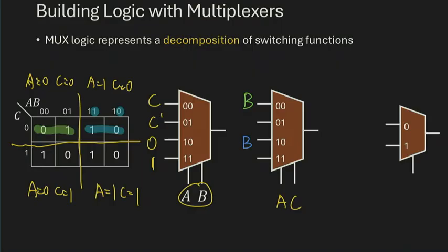And what about the next? Well, I can do 0, 1. Output is the complement of B. So I put down the complement of B. And finally, the last bit, 1, 0, that is just B. All right. So K-map or mux implementation corresponds to a way of cutting the K-map, essentially assigning a partial condition on some variables and then representing the remaining function using the missing variables.